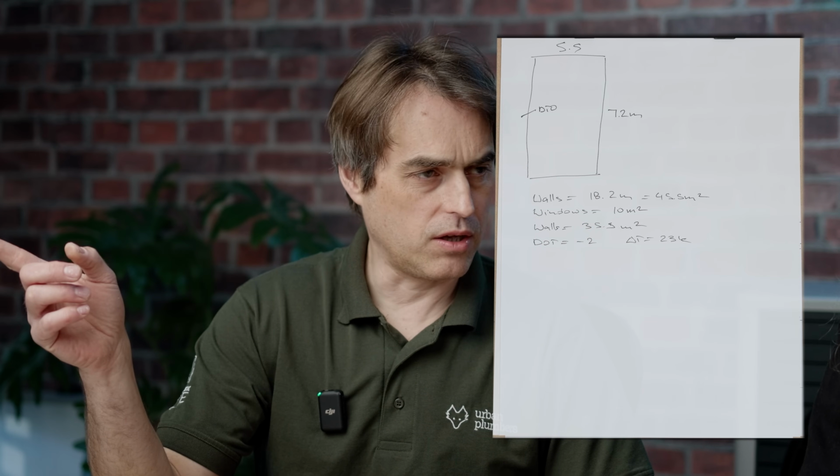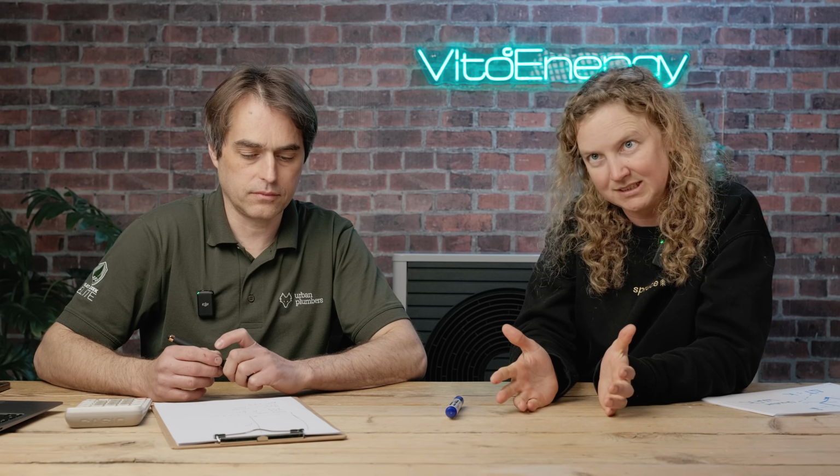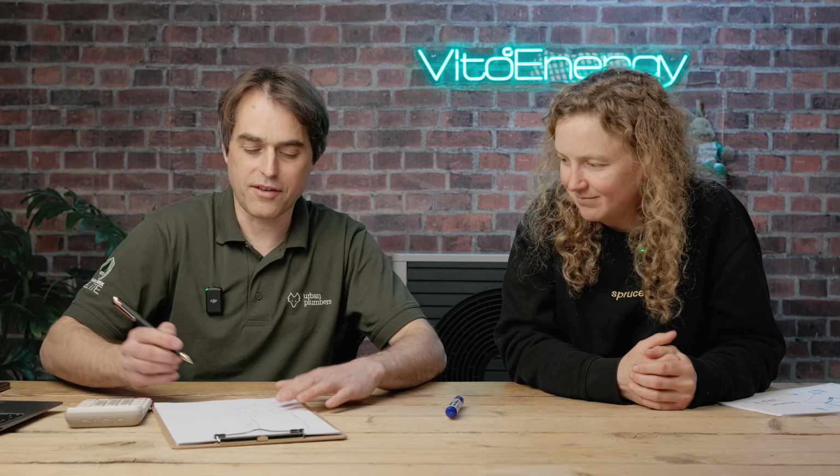Those are high quality double glazed windows. What U value are those? How do we know that? So you could get manufacturer's data, but normally you would look those up either from, again, the CIBSE design guide, or if you know the new build spec, what the regs were at the time, then you can use the regs at the time. What do we say those are? 1.8. Yeah, that's what I thought.